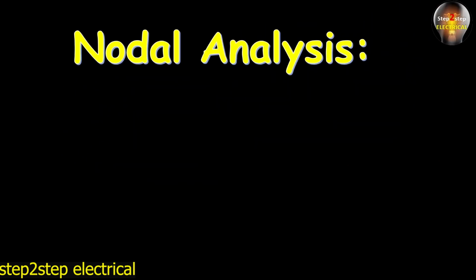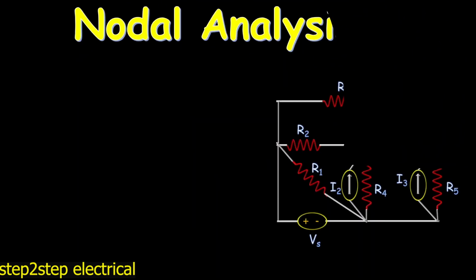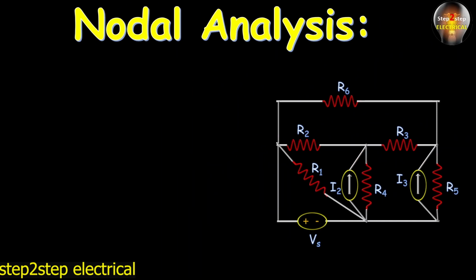Now we are here to discuss nodal analysis, and this is part 4 of nodal analysis, and in this part we will discuss type 3 circuit. As you can see here, this is a circuit. In this circuit there are current sources along with a voltage source. But as we have discussed earlier in the previous video, the voltage source must be in series with a resistance. But in this figure you can see that there is no series resistance with the voltage source. So we can conclude that this voltage source is not transformable into a current source.